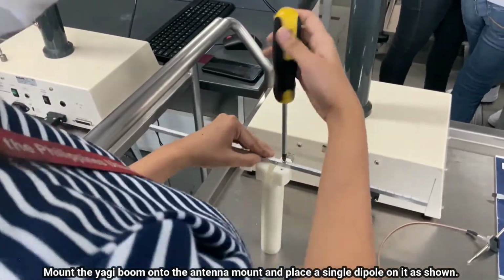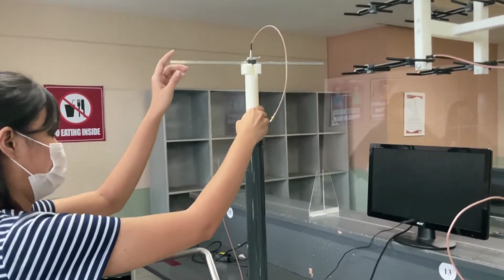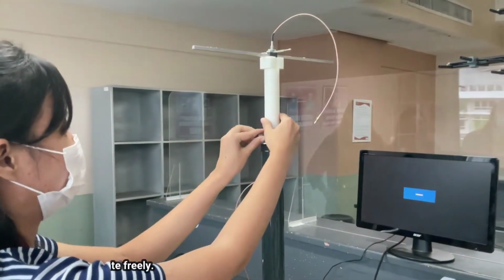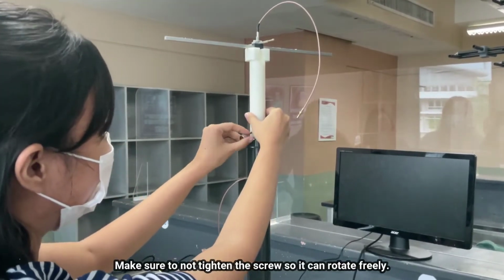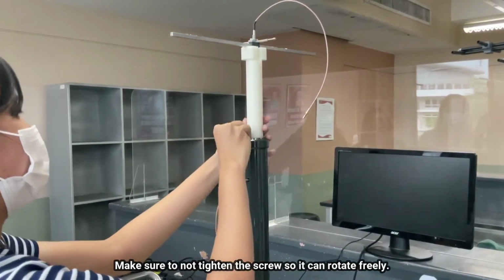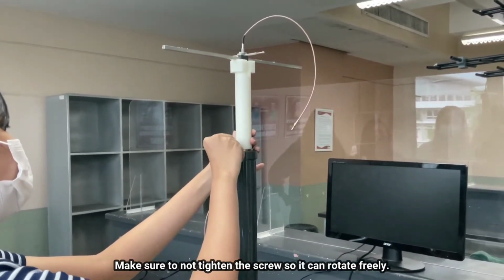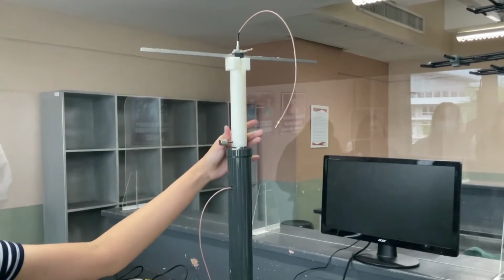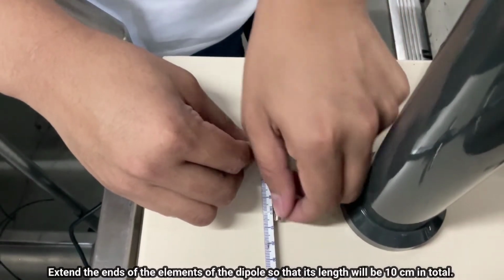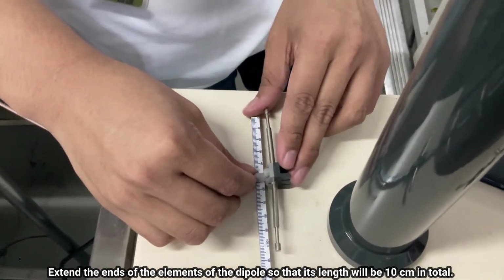And then, mount the Yagi boom onto the antenna mount and place a single dipole on it as shown. Make sure to not tighten the screw so it can rotate freely. Make sure to extend the ends of the elements of the dipole so that its length will be 10 cm in total.